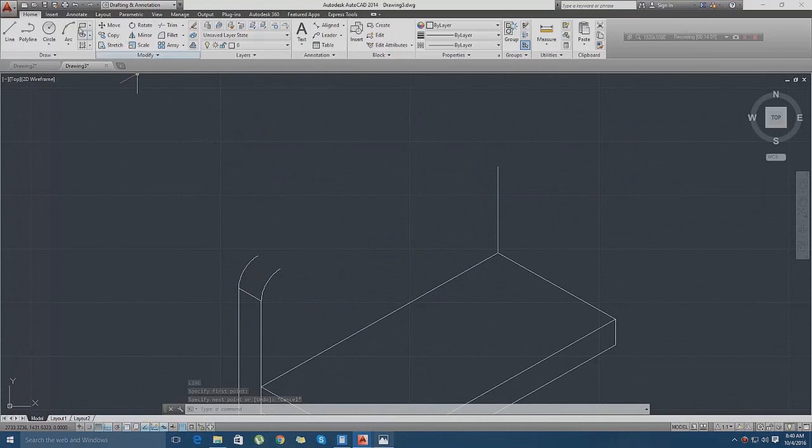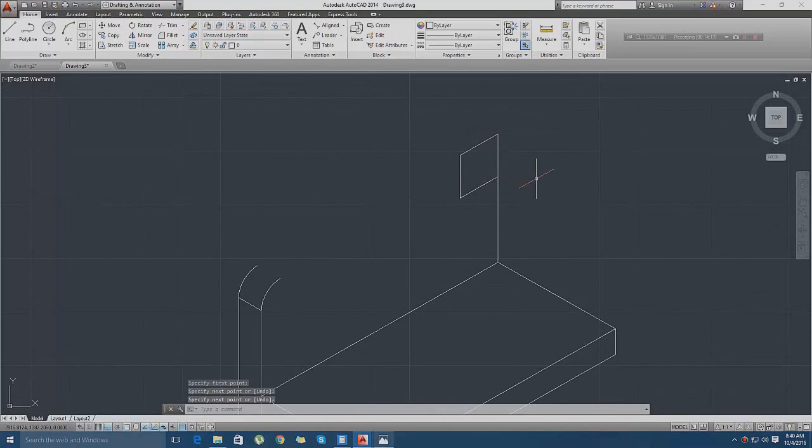Okay, fine. Now I'm going to draw this ellipse, which is line, the same thing, 20, 20, 20, 20. Okay, fine. Simple. Just draw the same thing that you have drawn on the opposite side. Ellipse 10. Just trim using the trim command. Trim all those unwanted things. You just have to know.